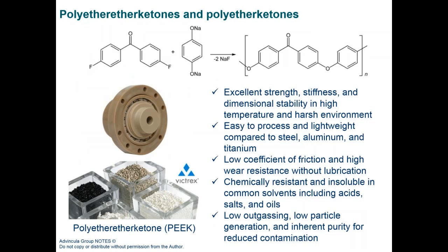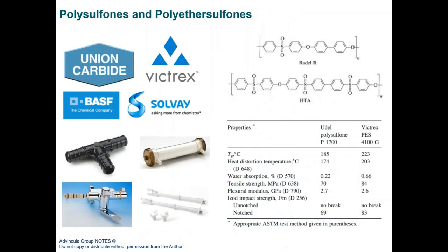And several companies are producing this. Polysulfones and polyether sulfones are very good polymers, with high melting point, very good distortion properties, and low water absorption. And again, these polymers are used as metallic replacements.